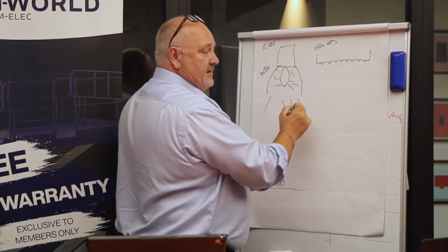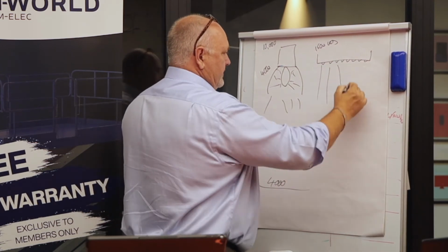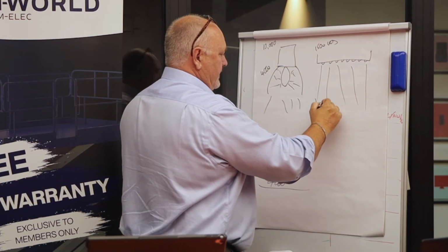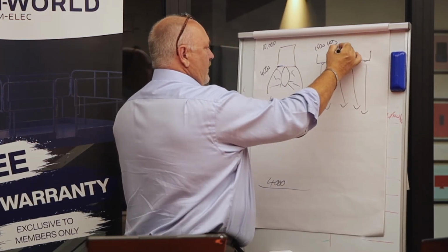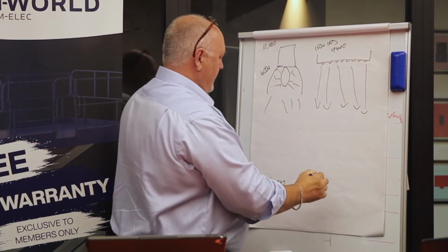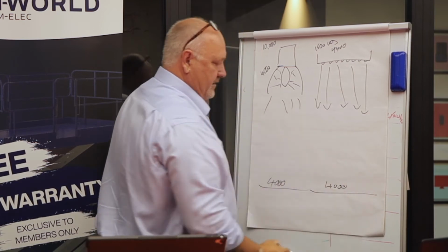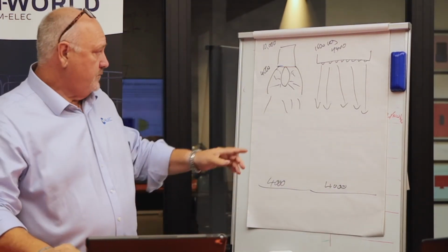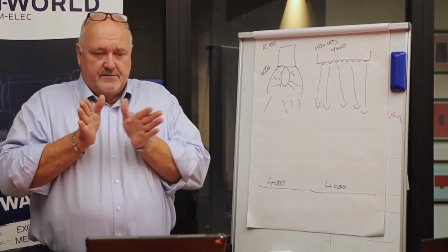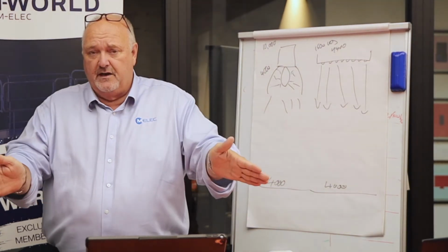The light that they send down is like this, so it's all heading in the right direction. So this is only 4,400 lumens here, but at this level here, we still achieved 4,000, simply because each one of these is projecting at between 90 and 120 degrees.